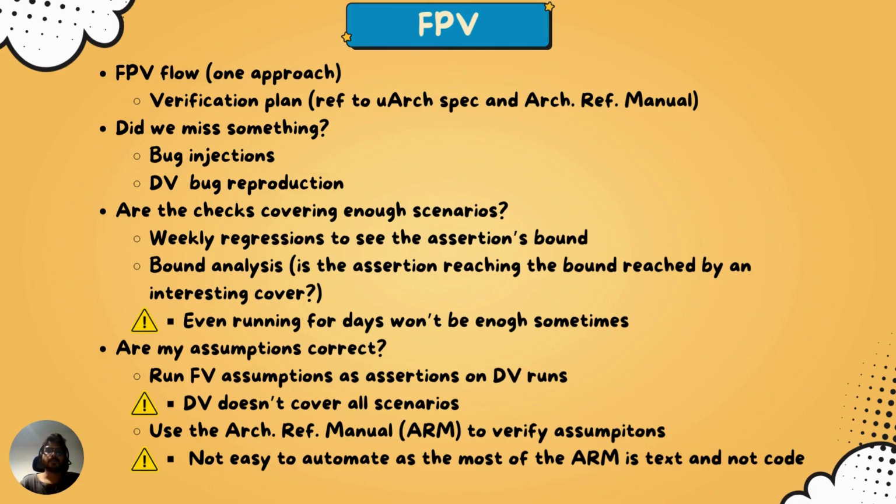properties. One is called assertions, where you write a property which is supposed to be always true, or which is supposed to be true for the conditions that are specified in the property. And if it fails, that means you need to debug and you need to find out issues and you need to fix your environment or so-called assumptions or constraints in the design, or fix the design itself if you find an actual bug. The second type of property are covers.